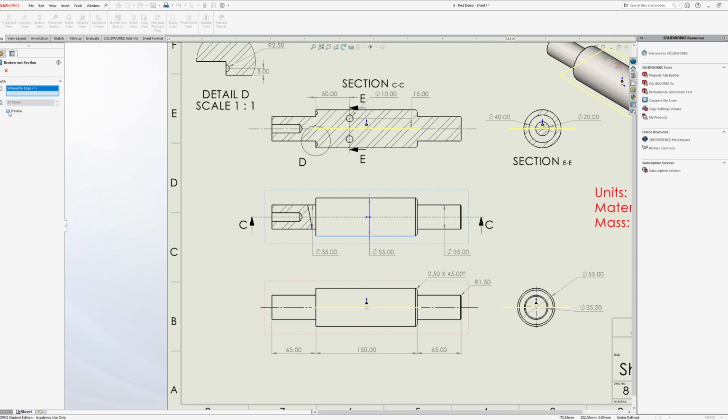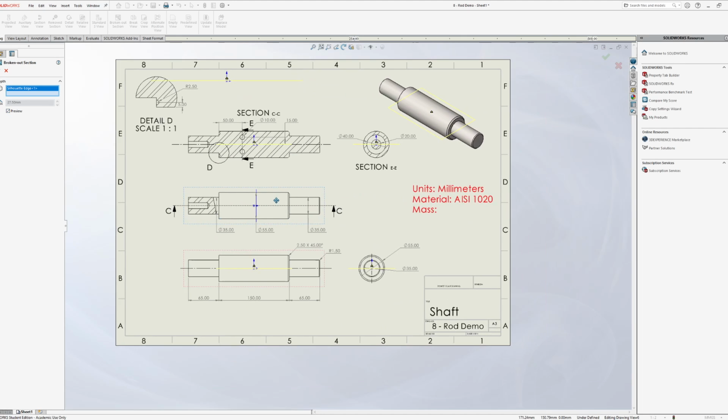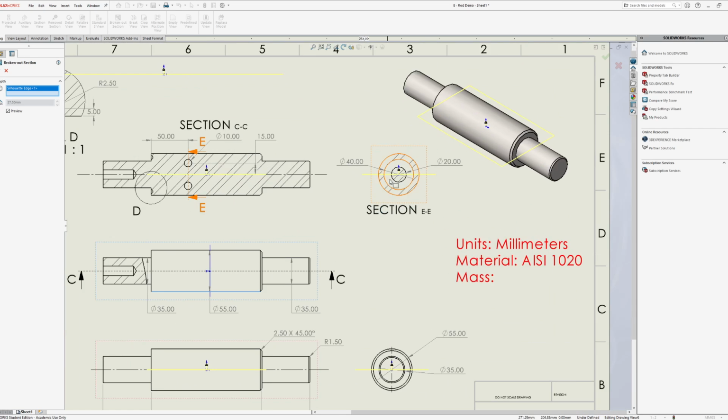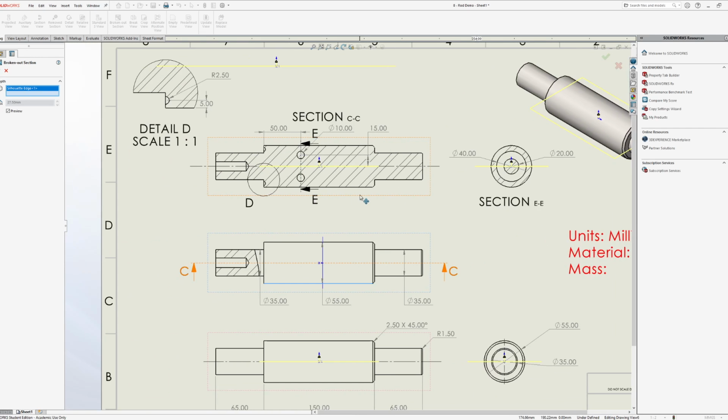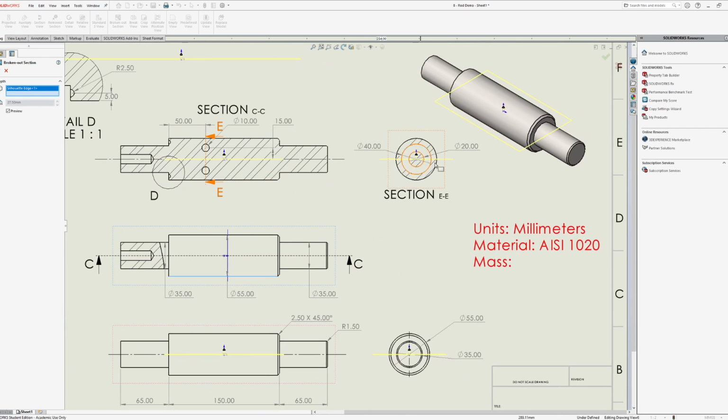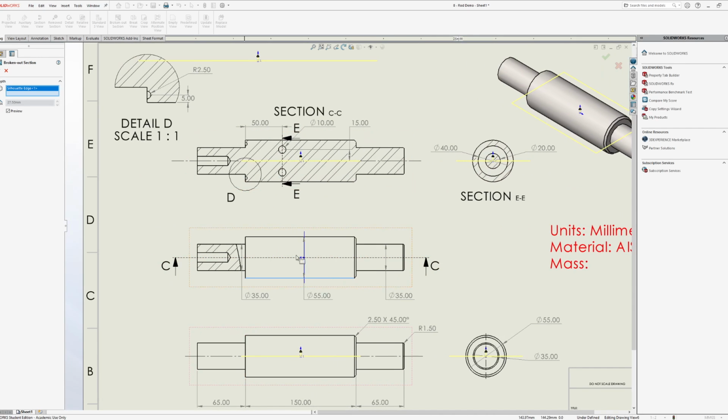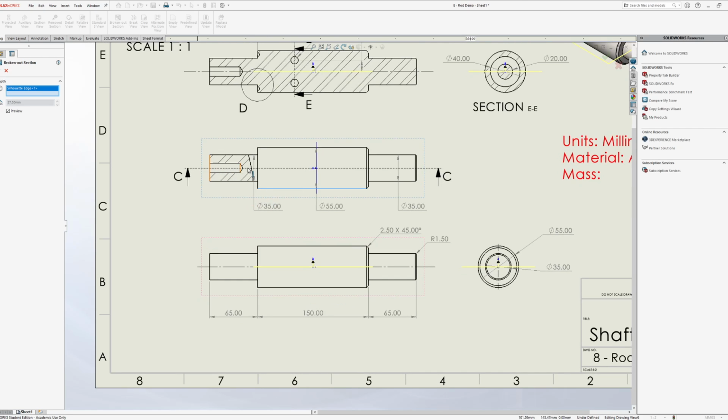Silhouette. Yes. This is also good. When you select that edge, it'll also show other regions, other sketches. You'll see these yellow planes here. That's showing where that sketch plane it's creating actually is. Thankfully, it's putting that sketch region directly where it should be, right at the middle.